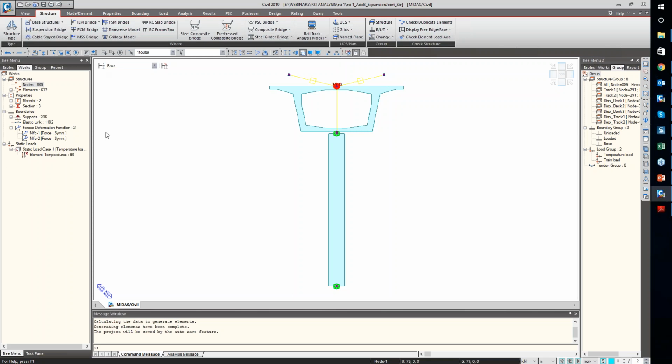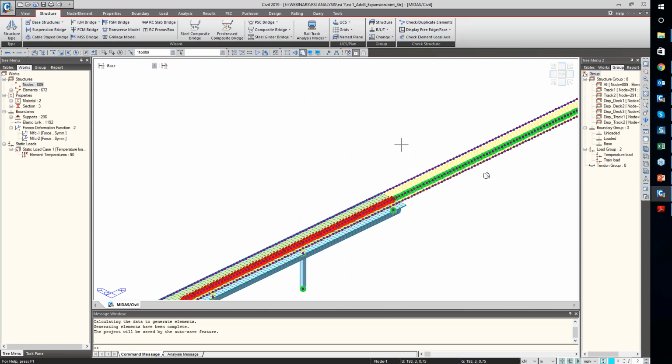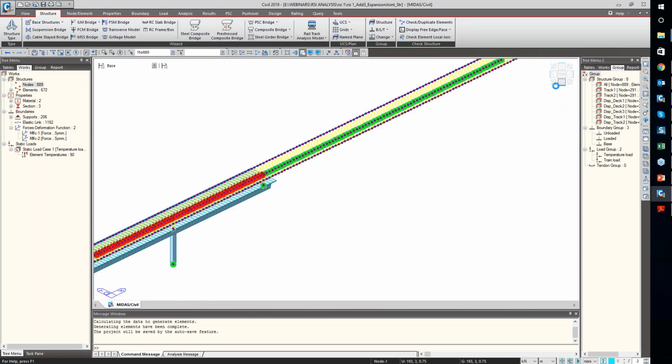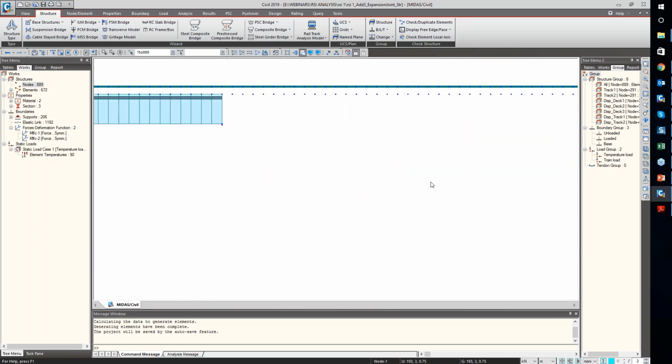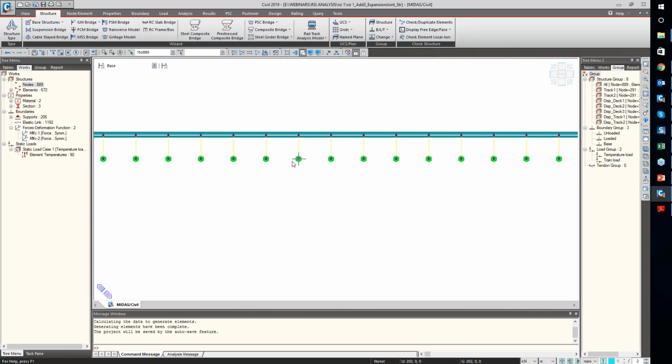Next, the boundary condition for my rail in the embankment. If you see here, this is my embankment part. The bottom point of my embankment is completely fixed, and the rail and my embankment are connected with the same multilinear elastic links. So this is representing my ballast, whatever ballast is available. Depending on whether it is loaded or unloaded, it will have that multilinear link stiffness of loaded or unloaded.